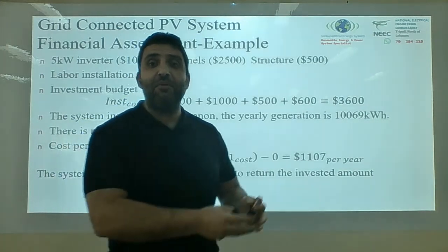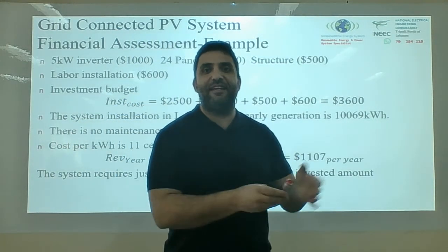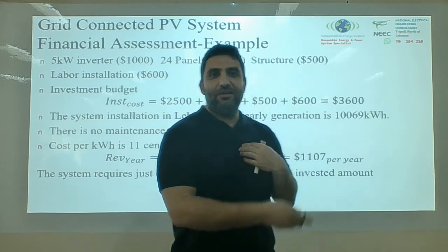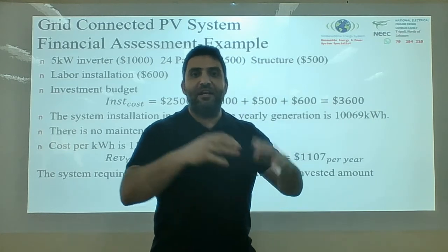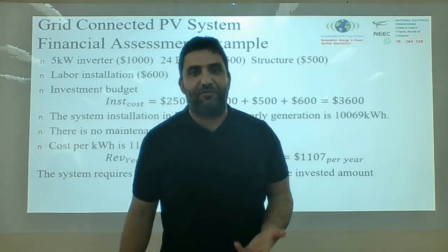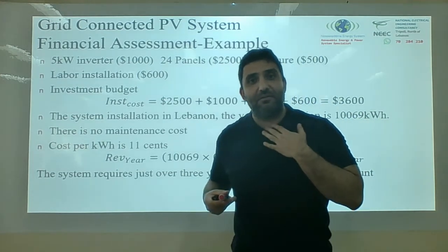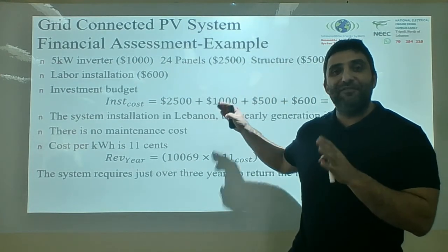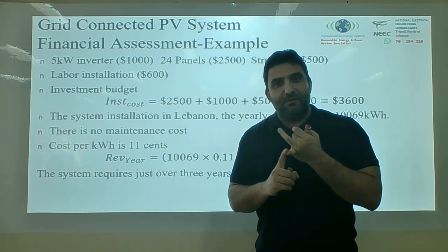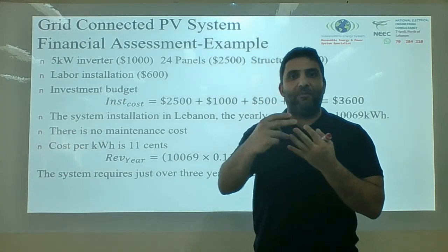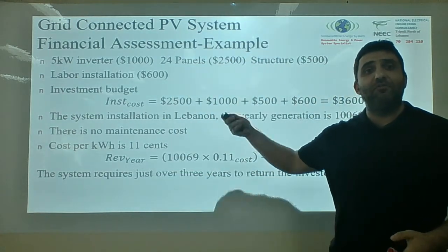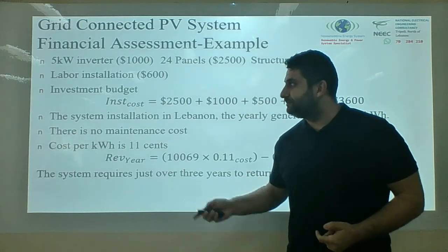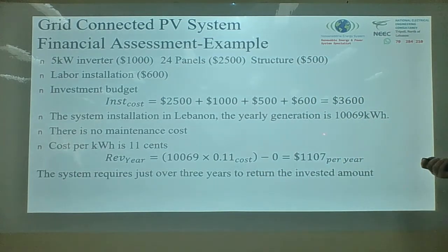What else do I have? The inverter. Some inverters have a warranty of 2 years, 5 years, 10 years. But can you check the inverter cost? The inverter cost is, for example, $1,000. It's not the entire system cost, so even if you have to replace it after 5 years. Guys, based on my experience, a standard inverter, if you don't overload it from a DC or AC perspective, you protect it from lightning, and you do all the proper protection and proper installation, will last between 5 to 10 years. What else do you have? The infrastructure that you installed could last for a long, long time.